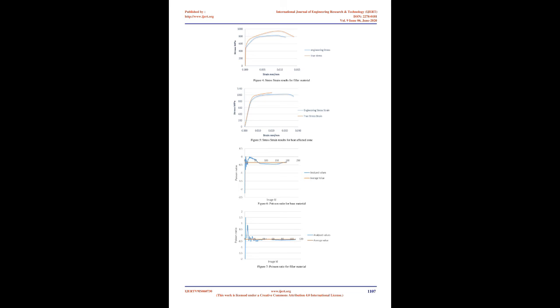From Figure 5, the strength of the heat-affected zone is observed to be much higher among all the 3 specimens and yield strength is found to be more than 800 MPa, which is approximately 830 MPa. The increased yield strength of the heat-affected zone may be due to the excessive heating process during welding of the joint, and it may change the microscopic crystalline structure of the material resulting in a new chemical composition of steel.